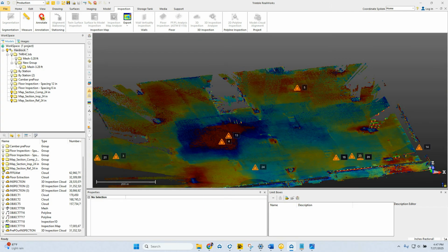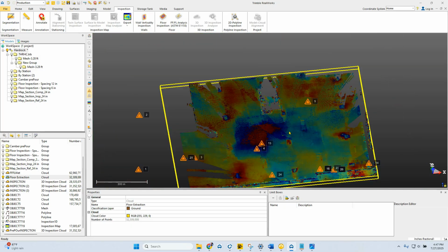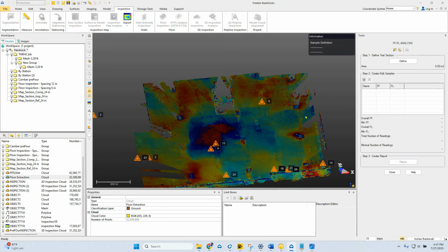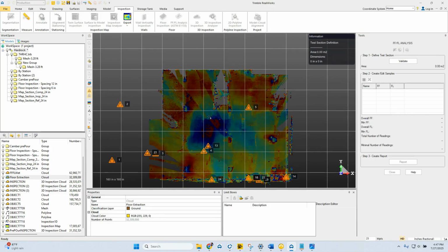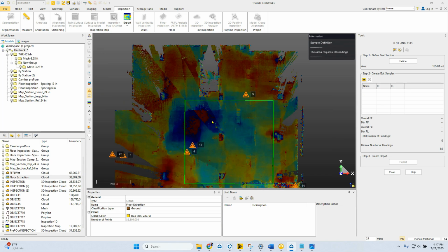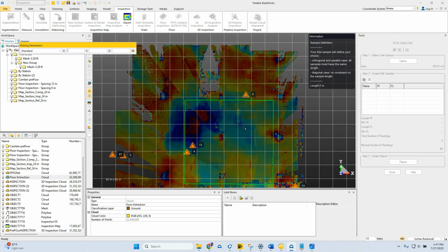Moving in here, the other nice thing we can do here is with the post pour, essentially the flat concrete, I can also do FFFL. So this can be done in Field Link, but can really be tightened up here in RealWorks. What's nice with both programs is I can, and this was during a wet pour, so they were actually still filling it or floating this and bumping this. I actually kind of ignored this until they were done doing that.